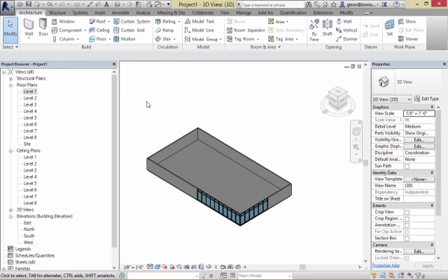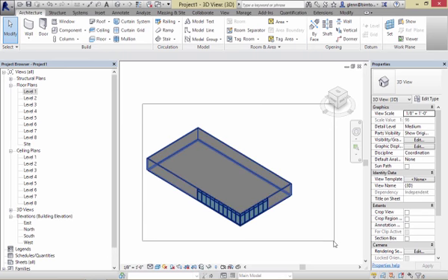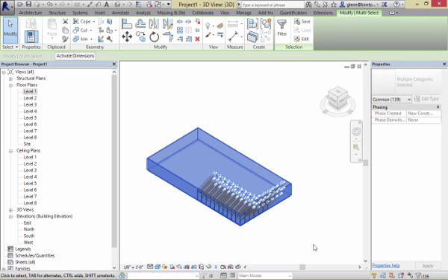If I want to make a multi-story building, what I'll tend to do is just grab it in 3D. You can use whatever mechanism makes sense. Okay, I grab 4 walls, some curtain walls, some floor. You'll see the curtain wall always has pins in it. That's because it's a pattern-based curtain wall, saying those things are locked in rotation.